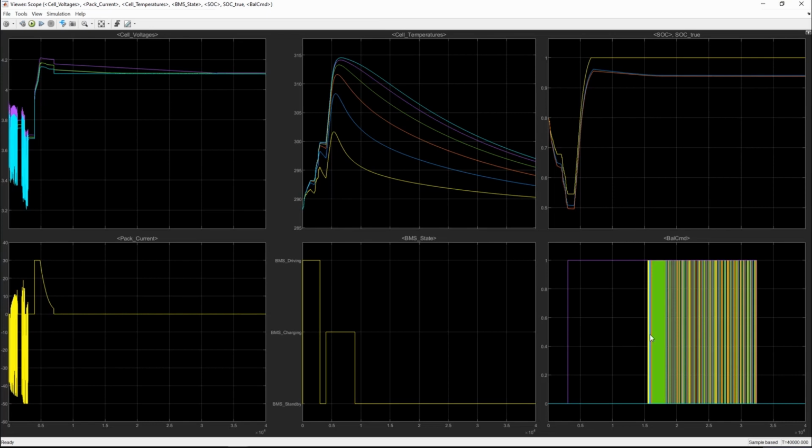The temperature traces show a significant difference among the hottest and coldest cell. The reason is mainly the asymmetry in the module layout in terms of thermal behavior. So cell number 6 gets significantly hotter than cell number 1 because it is thermally insulated on one side. Even when the maximum temperature reached during this simulation is not of immediate concern in terms of safety.